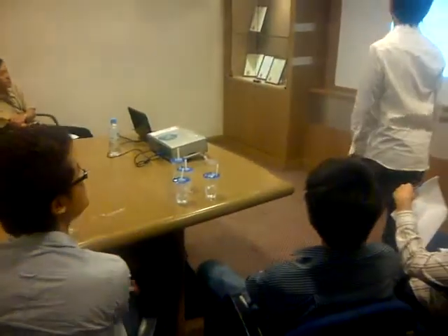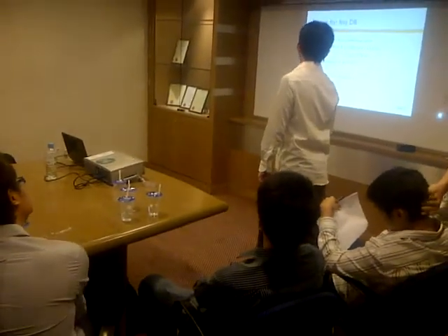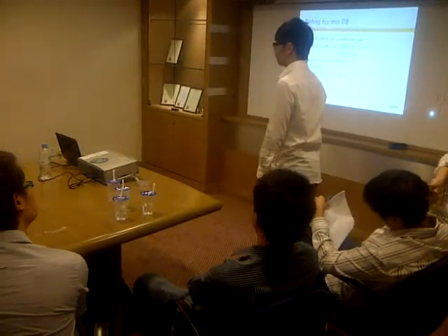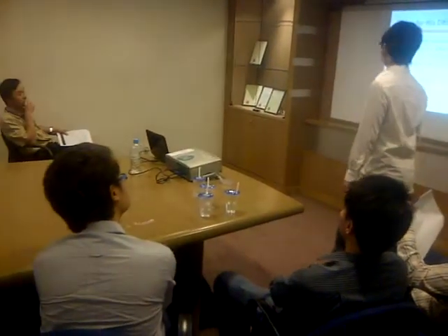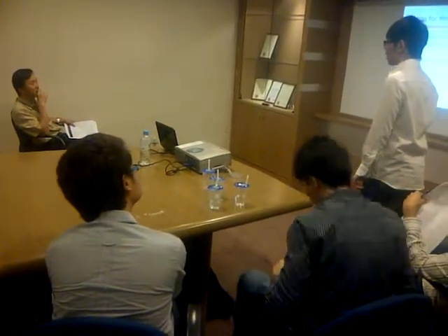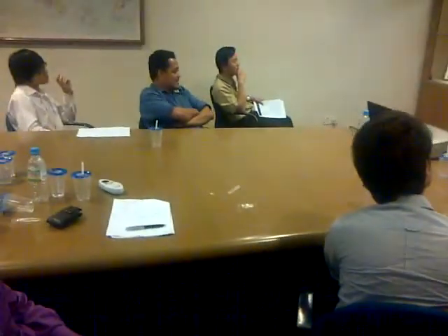The MCCB used is about 400 amperes, and the copper cable they use is about 185 millimeter square. Maybe. Very good. I straight away look at it, your 400 amp is not so correct, without even looking at the thing. 400 amp is really oversized.